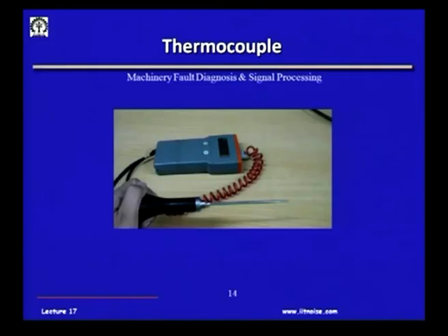Nowadays, many data loggers are there, which will just record this voltage, and then you will get a record of the temperature signal. Particularly when you are talking about temperatures around an engine, wherein we need to know the inlet temperature, the exhaust temperature. So, we can put all around the engines a lot of these thermocouple sensors.